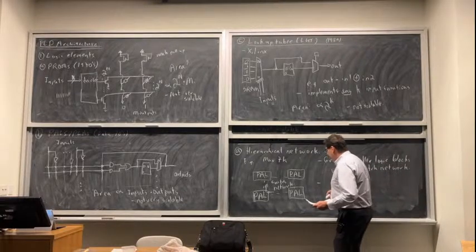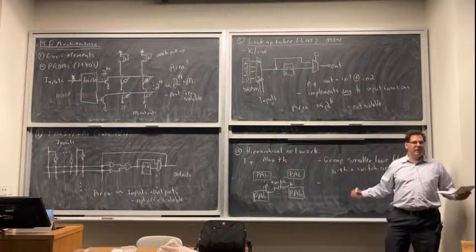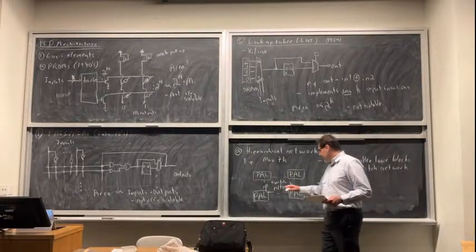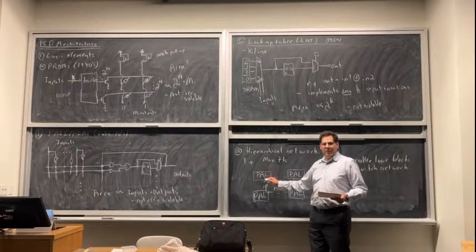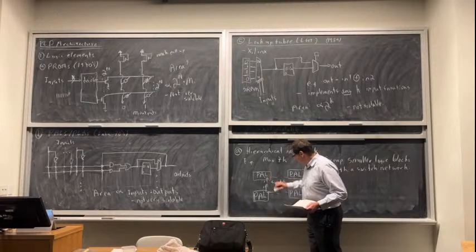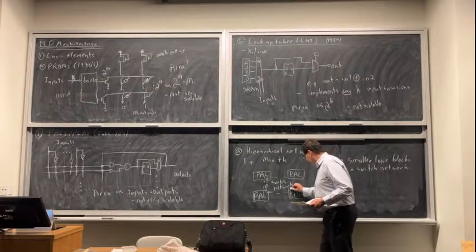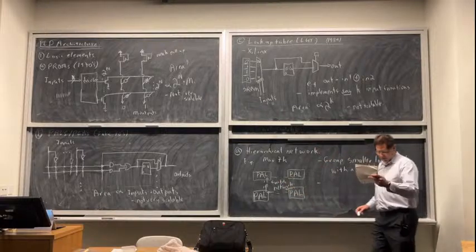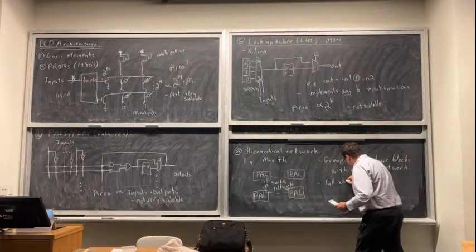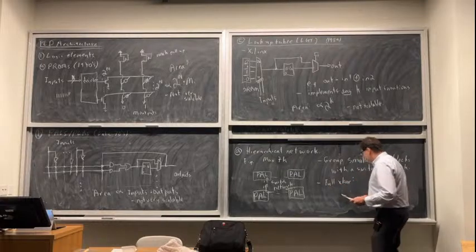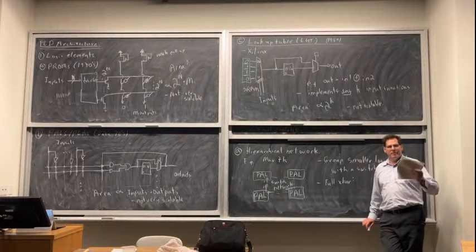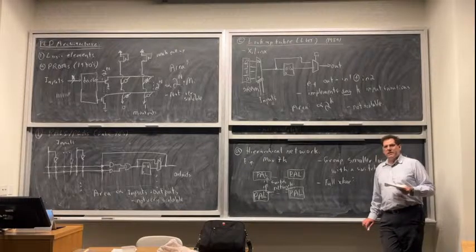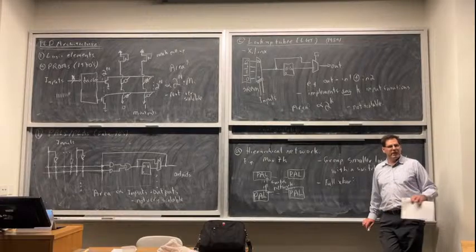Okay, so the easiest switch network that I can think of is, let's make a crossbar. Okay, so a crossbar allows me to connect any input of the switch, or any output from the switch network, which would basically be something going into one of these PALs, to any input. Okay, so some signal that went into the switch network. So we could use a full crossbar. So full crossbar, if you haven't heard that term, it means any output can be connected to any input. There's no restrictions, no blocking. It's like the nicest switch network you could ever have from that point of view.